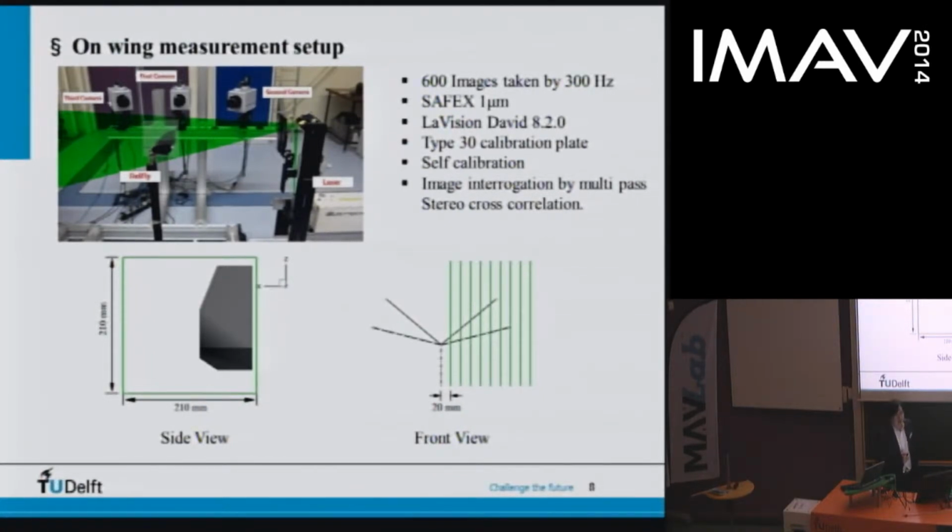During each case, 6 images are captured at a 300 recording frequency, a double frame recording frequency of the camera, to guarantee we have enough flapping cycles for the later ensemble averaging. Also, a CFX fog generator will generate water glycol-based particles with a mean diameter around 1 micrometer as the tracing particles. In the post-processing, LaVision DaVis 8.2 was used.